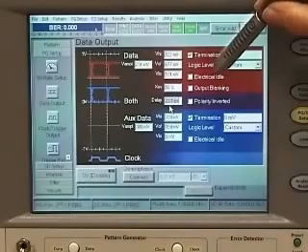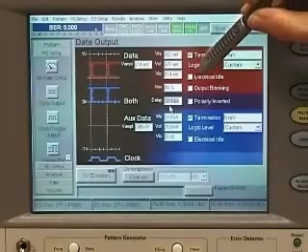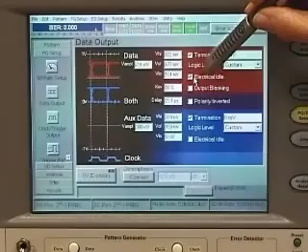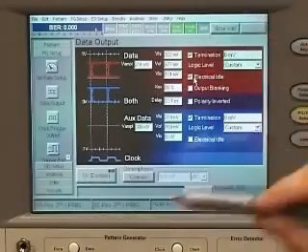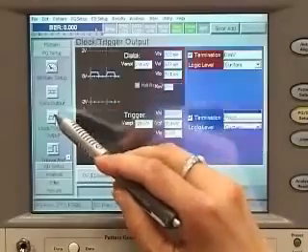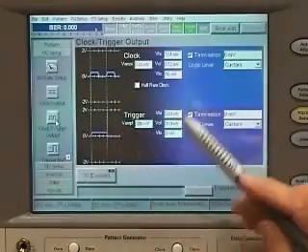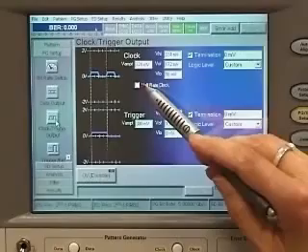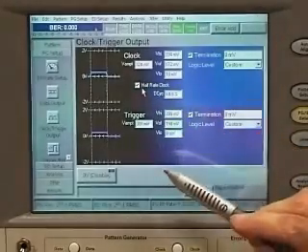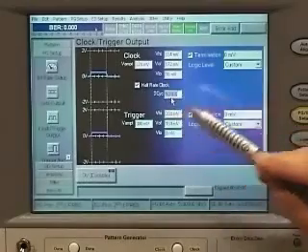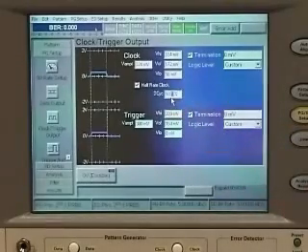Here you can turn on the new electrical idle mode on the generator output. And if you go to the clock and trigger output, here you can turn on the new half-rate clock mode for testing forwarded clock devices. You can easily change the duty cycle to emulate stress conditions of a non-ideal clock signal.